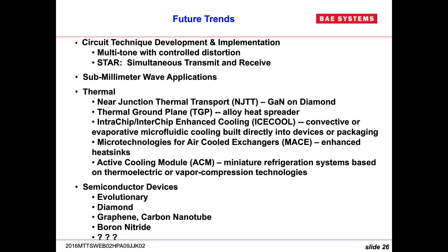Also, you're not at the point that you can build single-strand carbon nanotubes. So any FETs that have been built to date on carbon nanotubes are on a mesh, a disorganized mesh of carbon nanotubes. Because of that, your dimensions are very, very large, and you can't get down to the micron-type dimensions that you need for microwave frequency response. So although they show promise, they have a significant way to go before they can realize microwave devices.